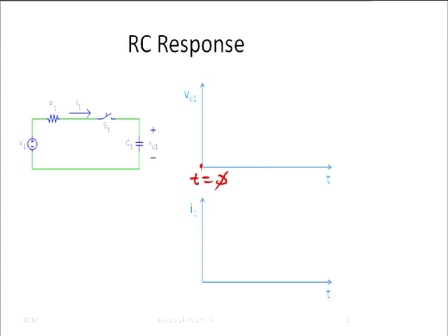What really happens is that initially, what is the voltage drop across the resistor R1, just when we close the switch? That voltage drop is V1 because on the left side of the resistor we have V1. On the right side of the resistor, the capacitor is still discharged. We have 0, so the voltage drop across that resistor is V1, and consequently a large current flows.